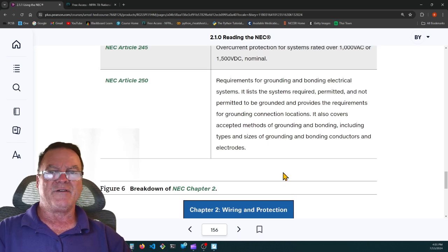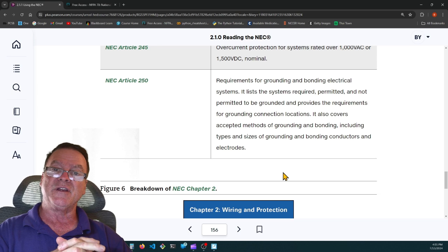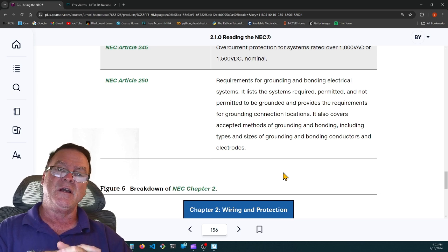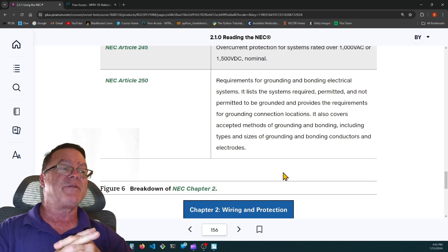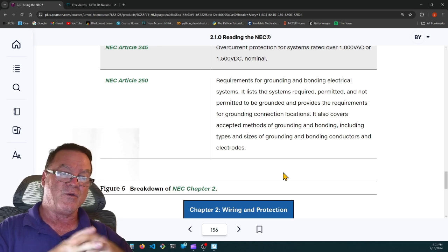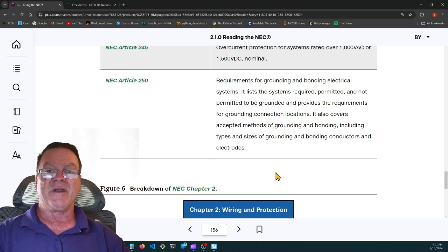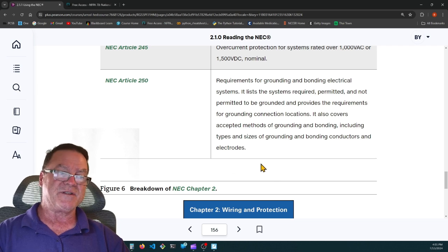You never want to have a difference of potential, when we're talking about voltage as a difference of potential. And you don't want a difference of potential between, let's say, your kitchen sink and the refrigerator. Because then if you touch the kitchen sink and the refrigerator, you could get a tingle, or much worse, you could be knocked down to the floor. You want to make sure that they're at the same potential. So all of the water piping in your house, the copper pipes, they're all taken to earth ground. They're taken to the same zero potential as the electrical system. That keeps you safe.